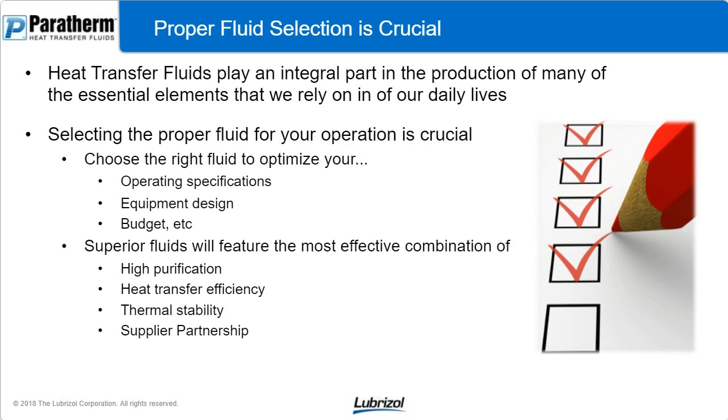How well does your fluid, your product that you're running through this system that's designed for thermal purposes, hold up to the potential damages, to the stress that a thermal energy transfer is going to put onto the fluid? That's not just important for the life of the fluid, but as a fluid gets stressed, it's going to break apart, it's going to degrade, it's going to foul the system. So a less thermally stable product will cause more damage to the equipment, more maintenance, more unplanned downtime, and really start you off in that downward spiral.